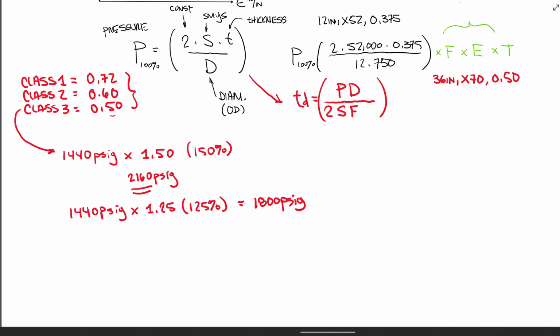And this is either for 4 hours, if we have a short fabrication section, and this is just changed for us internally to anything less than 170 foot of piping or fabrication assemblies, then we can get away with a 4-hour test. If it's greater than 170 foot, then we have to test for 8 hours for a minimum of 2160 and typically a maximum of 2220.